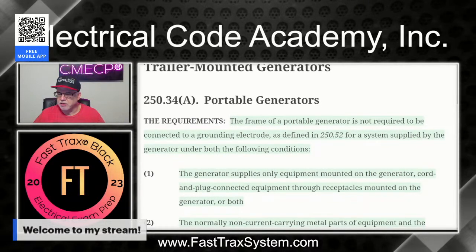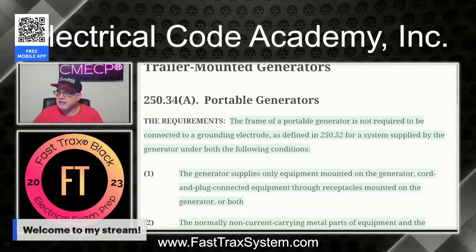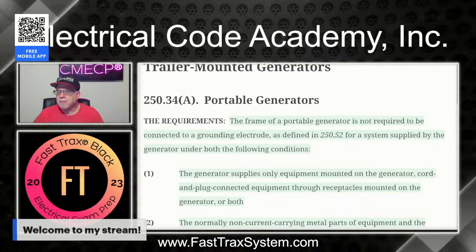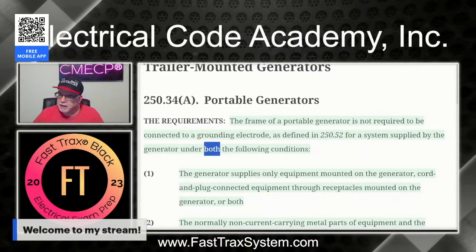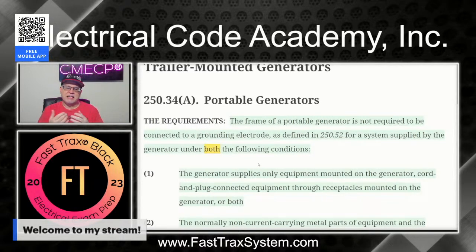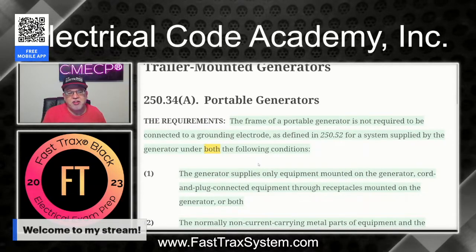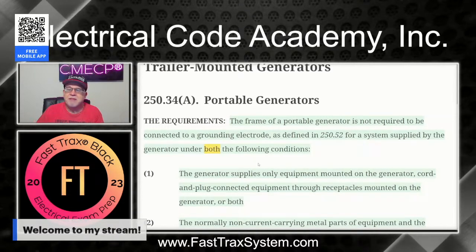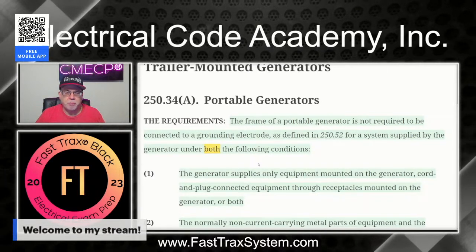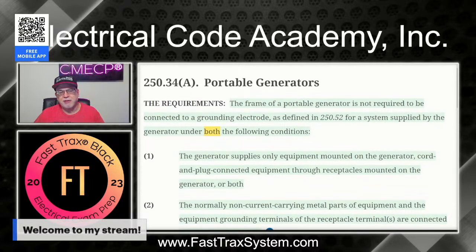So we'll be looking at 250.34(A) portable generators. Now, let's look at the requirement. It says the frame of a portable generator is not required to be connected to a grounding electrode as defined in 250.52 for a system supplied by a generator under both, okay, both, important to highlight that, both of the following conditions. So what this is basically saying is, okay, I have a portable generator and I do not have to drive ground rods or establish a grounding electrode system for this portable generator if the following conditions apply. And there's two of them, and you have to comply with both of these conditions, or the generator has to comply with both of these conditions.